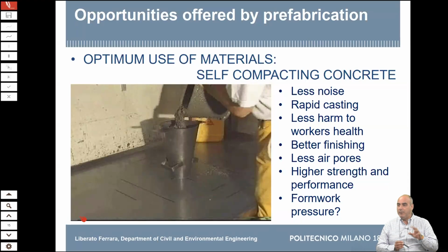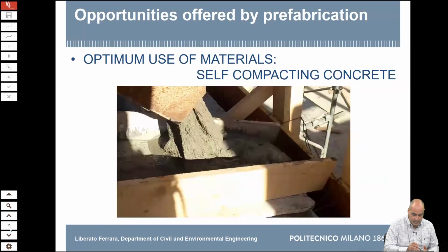When we think of how much I pay for concrete, that is one thing; steel is another thing; but formwork is another important cost item. In cast-in-place construction, sometimes you cannot use formwork more than a few times, whereas in the precast industry you can design steel formwork and so on. You can also optimize that issue as well.